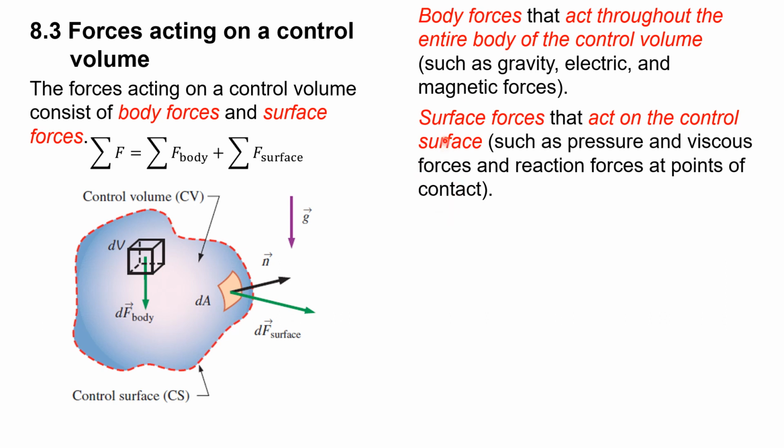At the same time, we also have surface forces. Surface forces act on the control surface. They can be in the form of pressure, they can be a viscous force, or they can be a reaction force that we can calculate at the point of contact.